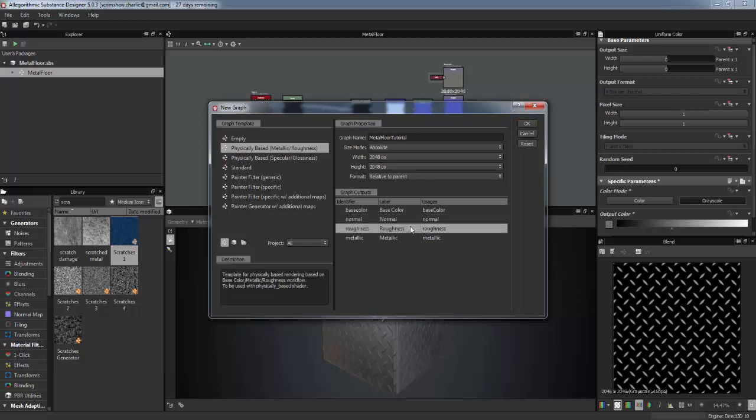Roughness will control how shiny or how matte a material can be. So with a metal, it's likely to be fairly shiny depending on the metal you're making. Then you have the metallic, which means that you're just assigning metallic or non-metallic properties to the material. So with that basically covered, we'll just start making the material now.